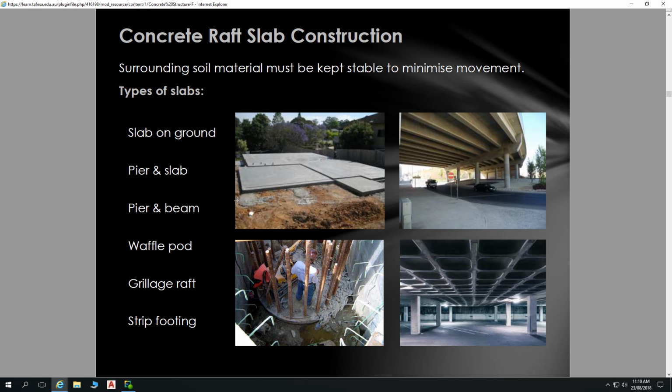So it's being a little bit more efficient with those materials. We could just go, all right, let's do a massive piece of concrete here, but at $300 a cubic metre, that adds up. To design it so you just have deeper edge beams, if you don't have a great deal of shearing forces coming from the side, can work in scenarios.